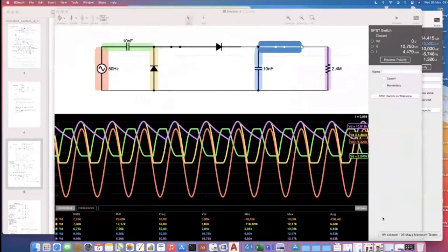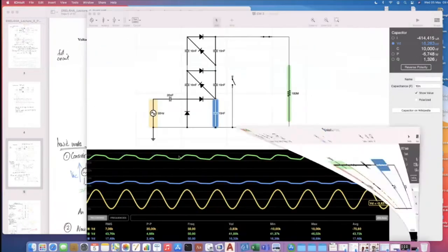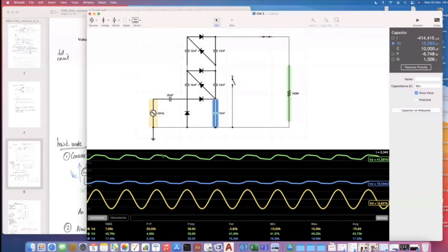If we look at that ripple, you can see it's quite smooth. It charges on the peak, going up to the peak of the waveform, and then falls as the waveform goes negative. Here it's got a bit of a different shape. Right, so again, it's charging as it goes to the peak of the waveform. It's discharging as it goes down, and then there's a sudden little drop there just before the negative peak of the waveform. Right, that's due to the switching of the diodes.